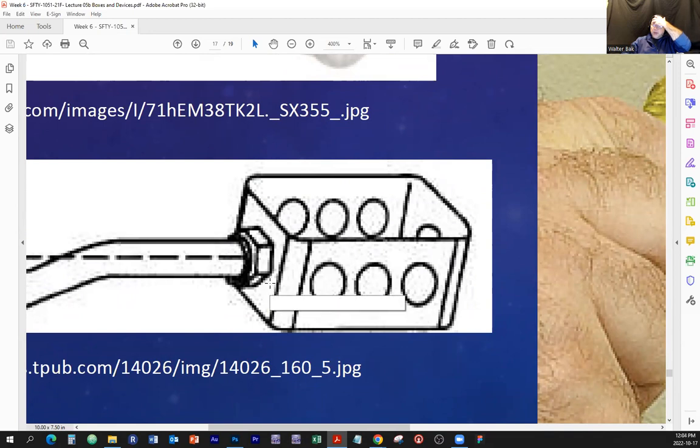So what you can do is you can bend that pipe to create something that's called a box offset, so it accommodates the height. And the rest of the conduit as it continues down the wall is actually touching the wall or timber frame, so it is actually mounted properly and fastened. So you're going to create a box offset in our second last lab.